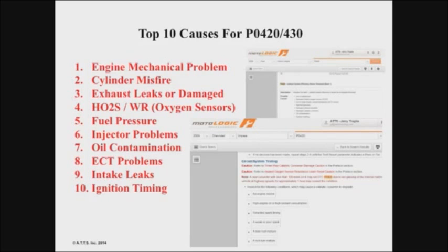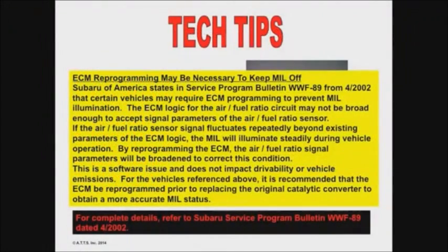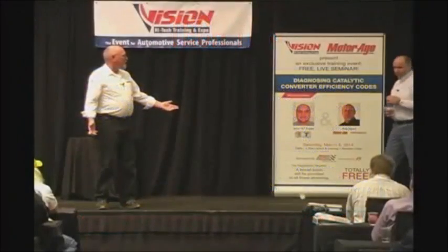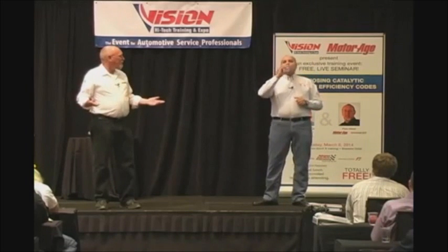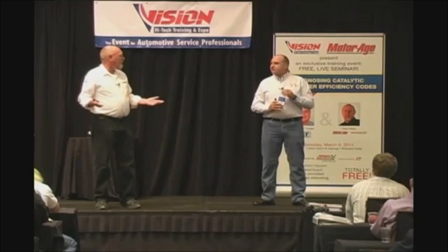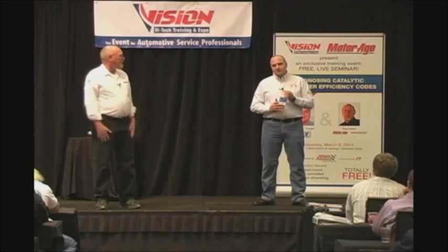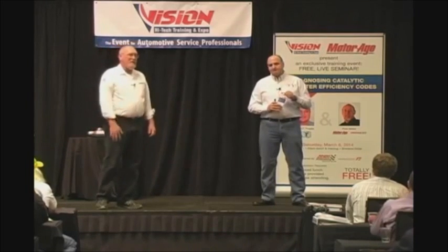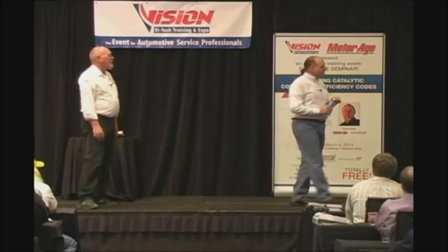Yeah. Can I interject in 1 second, bud? I'm sorry, I could be jumping in. Jump in. This is the fun we have, and one of the reasons it's so much fun doing these things live. I think all of the things that G had on his list, all 10, kind of have one thing in common, don't they? They all affect the quality of the feed gases getting to that converter. That's really the whole job for the PCM, isn't it? To make sure that those feed gases stay in a very narrow range, and when they get out of that range, what's going to happen to the converter? It's going to get overheated, and then all kinds of bad things happen. So they all have one thing in common: what's going in has got to be in that very narrow, acceptable range for it to handle.